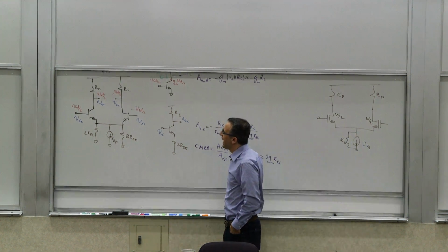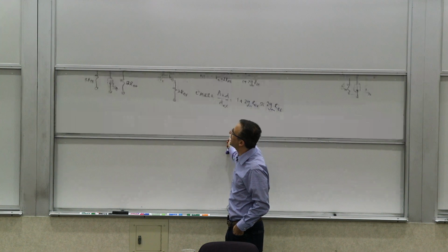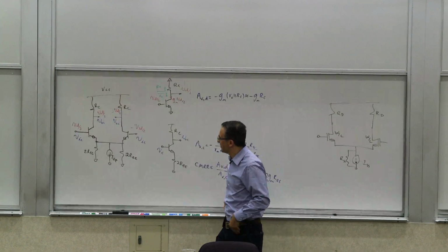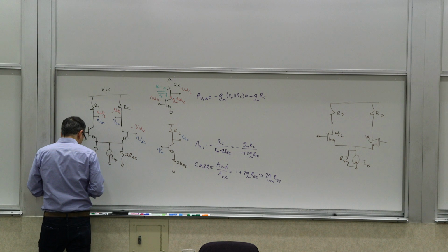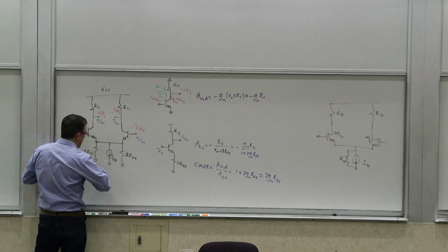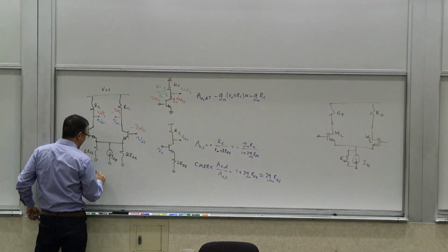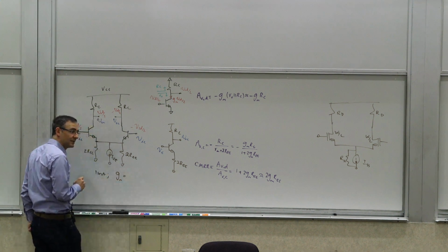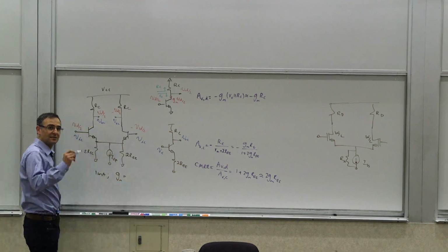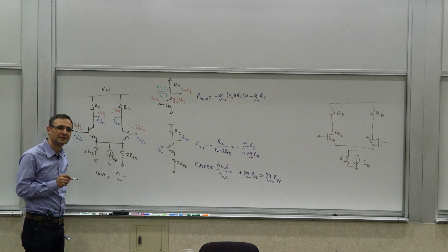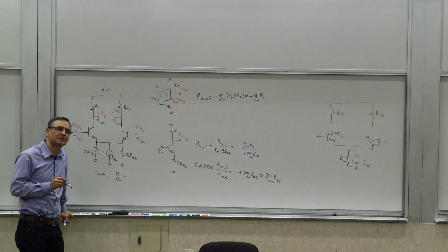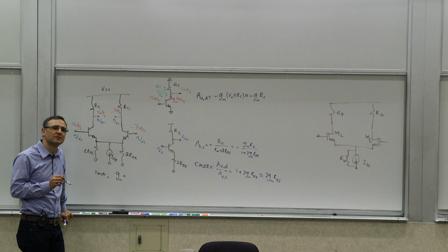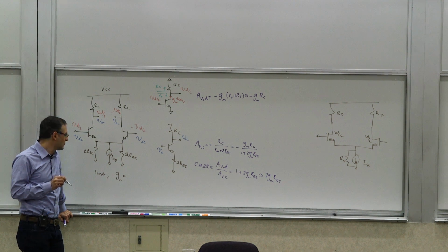The next question is, how do we increase the gain? We did some gain calculations, right? So for example, I'm picking some very nominal values. Let's say this were, I don't know, 1 milliamp. What is your gm for each transistor? Well, what if in your problem you have a completely ideal current source, so R_E is infinity, and A_CM is just 0?